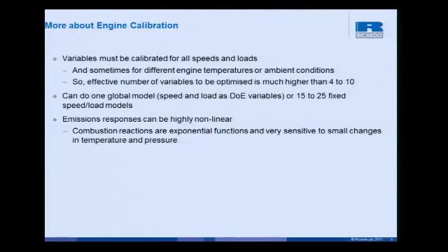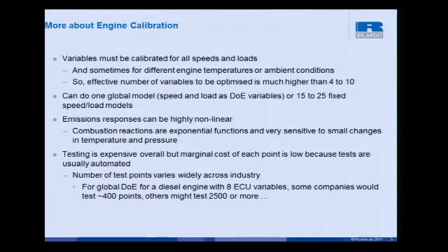Another is that emissions in particular can be very, very non-linear and sensitive to small changes in engine operation, and that means that you have some issues with test-to-test repeatability. The recent engine history, what tests it's been doing before, can affect the emissions in subsequent tests. So these are all things you have to take into account.